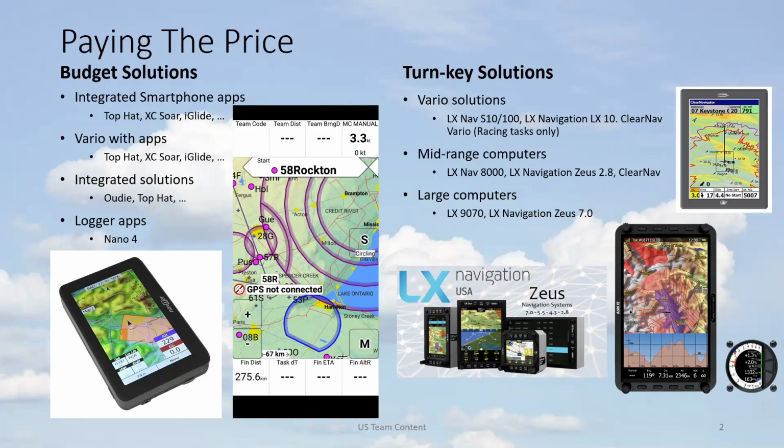It's a great point. The other thing is, if you are adventurous and have a weekend, you can take a Bluetooth transmitter and solder it into the back of a Kobo. I did that. The thing is about 1 centimeter by 1.5 centimeters, and there are 4 connectors. So there's 2 power connectors and a transmit and receive.